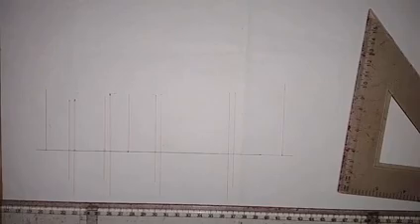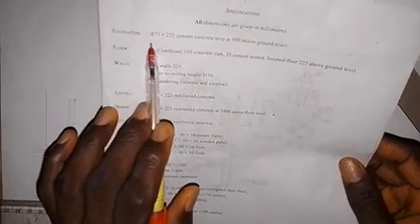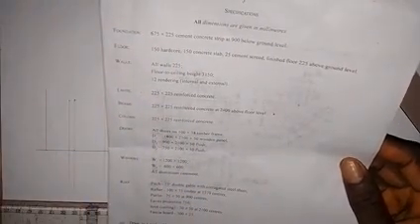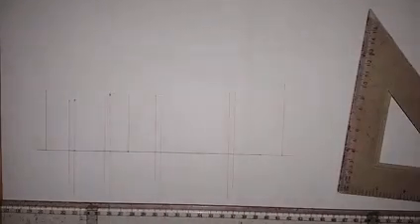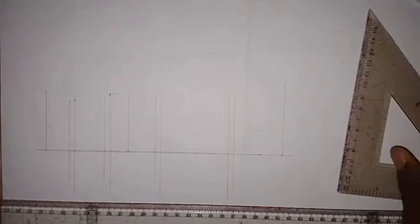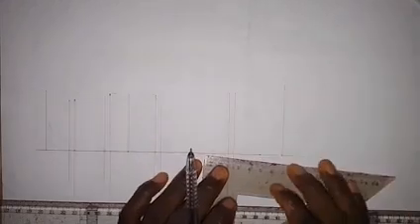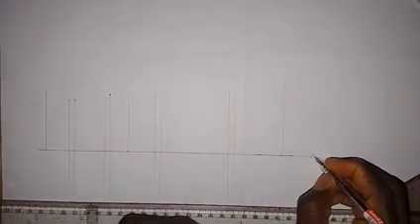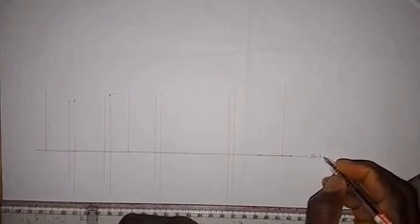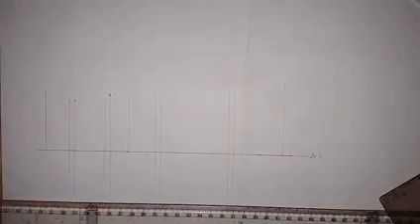Next thing that we are going to do is that we go to the foundation. For the foundation, we have 675 by 225 cement concrete strip at 900 below the ground level. Do not forget that this line here is the ground level, so I need to indicate that. This is the ground level line, and we indicate that with GL. So now, 900 below the ground level.